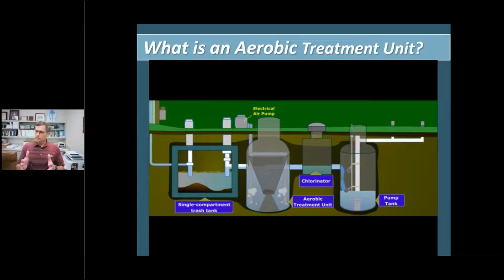in a smaller footprint, smaller geographic area, because if you have enough land, you could conceptually build a lagoon to handle enough of your treatment. You just think about the number of people, the number of gallons per day that may be used, multiply that times a 45-day, hopefully treatment cycle, and that's going to give you a volume of water. You divide that by 7.5, and that's going to give you cubic feet. And then you just think about how big of an area do I need.